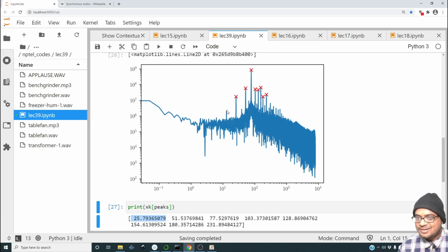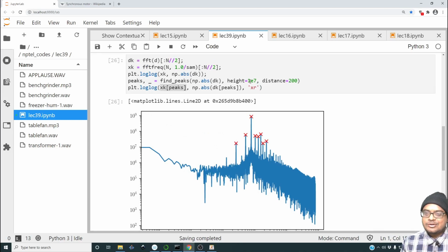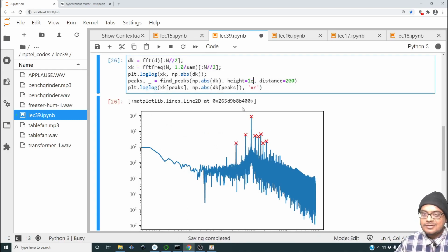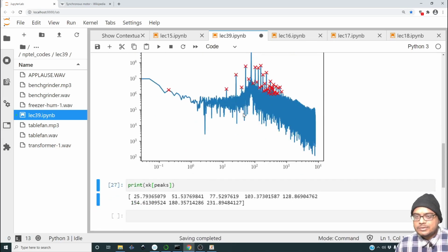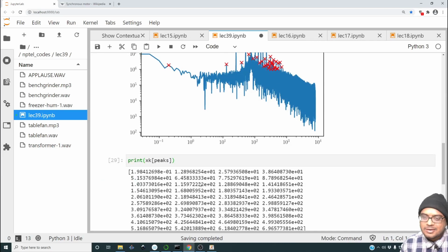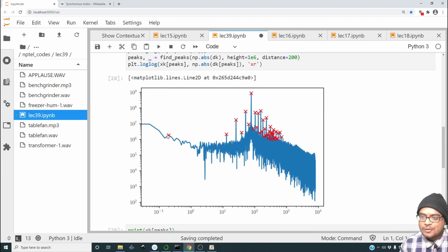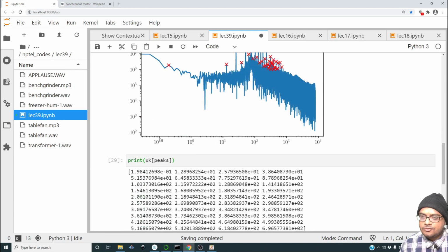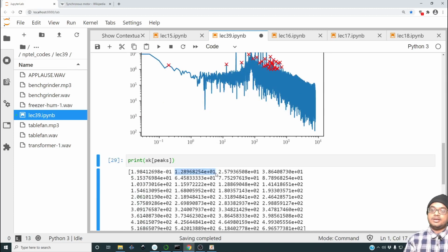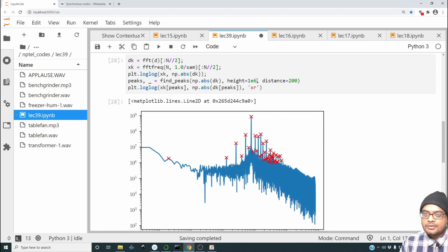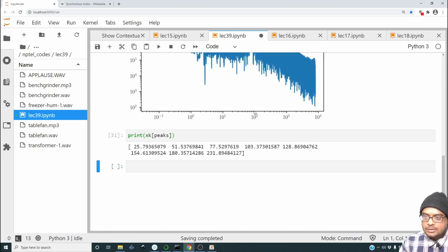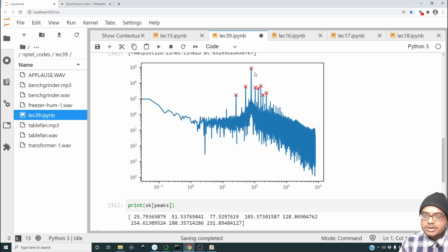And I'm going to bet that this is something like 12.5. So let me just reduce the threshold of the peak finding function. Let me make it 1.6. Let me run it, and let me see what this contains. Okay, it contains a bunch of values because it's grabbing this as well. I don't want to grab this. Well, it should be the second peak, and it is actually 12.89. Good enough. So we are getting all those harmonics. Let me revert back to 1.7. So the real peak occurs at something like 77. Now, we're gonna go with the primary peak, which is 77.